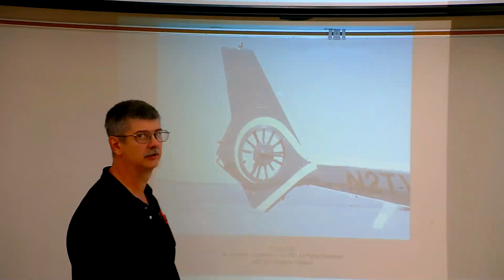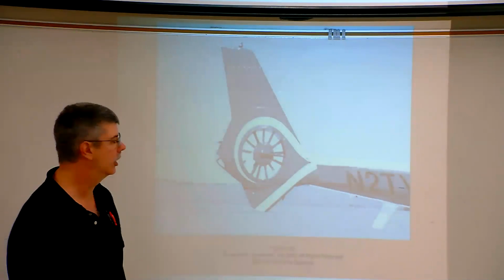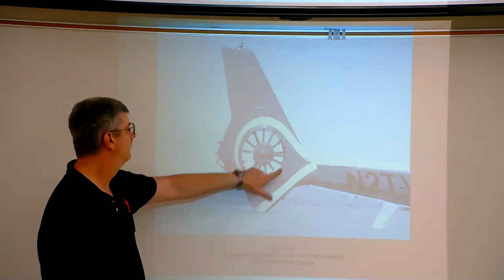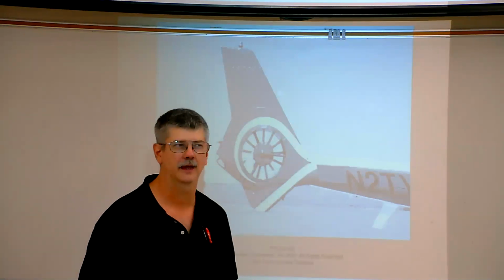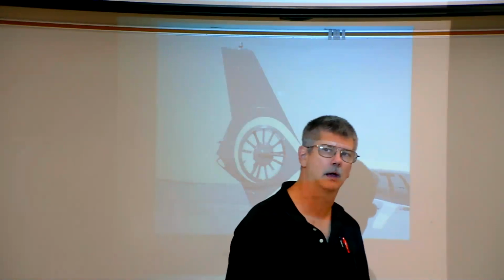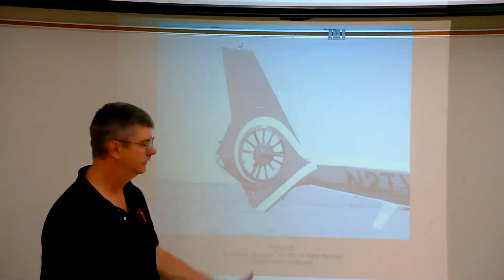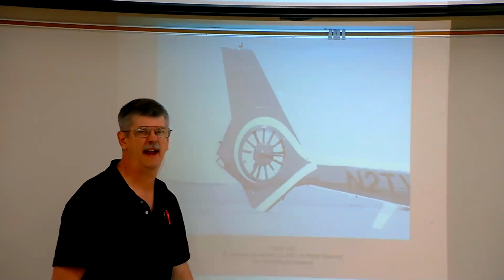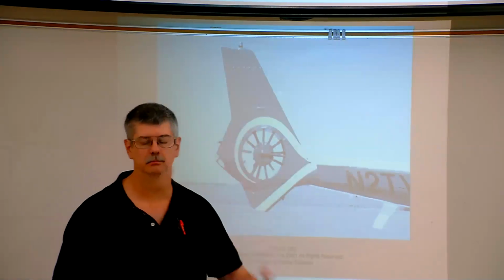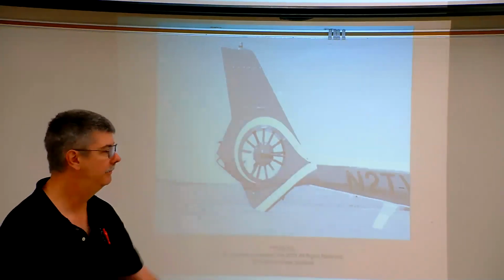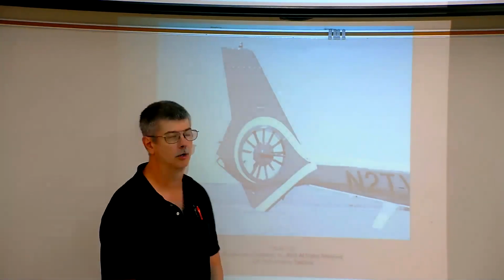We have all different types of tail rotors. Typically, you know, there'll be an open rotor, okay? But you may have seen the helicopter that the Coast Guard uses quite a bit, which is the Dolphin. It has what's known as a Fenestron tail rotor. Basically, it's a big fan with a ductwork and then variable pitch blades. Now, one of the biggest dangers on helicopters is the tail rotor, okay?